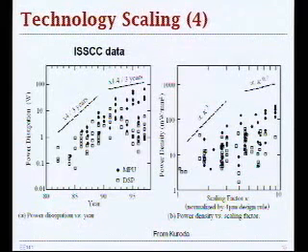Imagine taking a phone that is, I don't know, 150 degrees and then putting it on your head. It's not going to be really comfortable for you to speak into that device, and that's basically another reason. And then, for the reasons of constant voltage scaling, we had improvement in the density of our devices, but the voltage didn't decrease. So that led to a constant increase in the power density. Eventually it became a problem, and when we started scaling voltages, it leveled off.